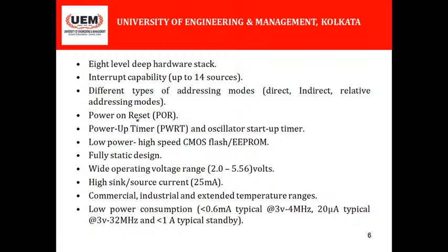Power up timer, PWRT. PWR stands for power and T for timer. So power up timer and oscillator startup timer, we are using these two types of timers for timing and control signal generation. Timer also decides how many T states are required to finish a particular instruction, when to start a clock cycle and when to end a clock cycle.